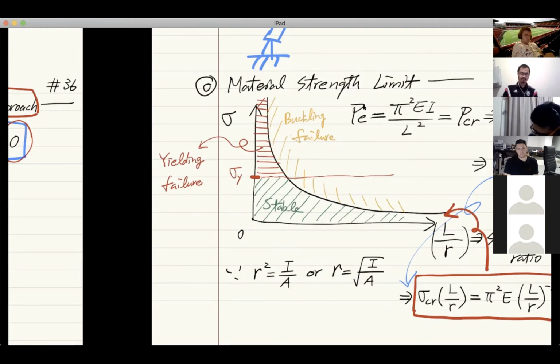In other words, as a structural engineer, you want to make sure that you're checking your calculation so that your expected stress and the slenderness ratio are appropriate. Slenderness ratio is coming from your design. Your stress, this one here, is coming from your loading. You can call it external loading.